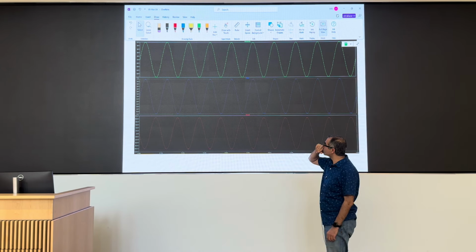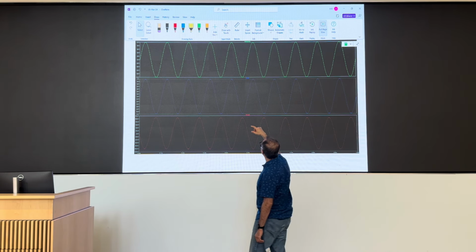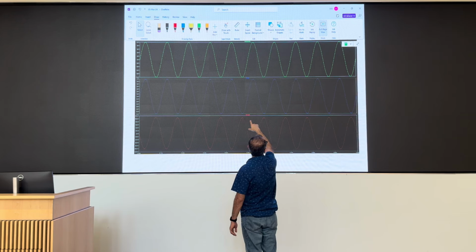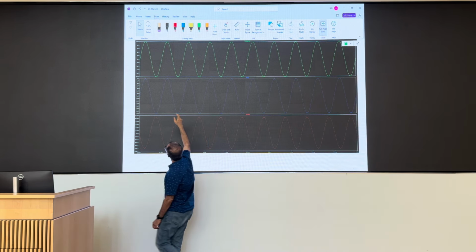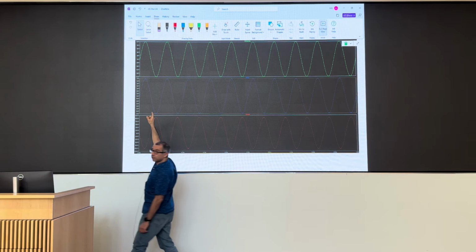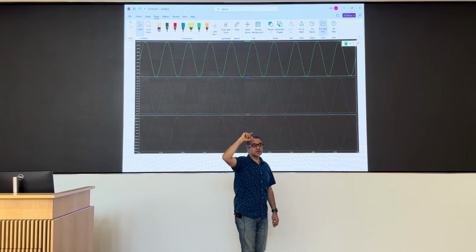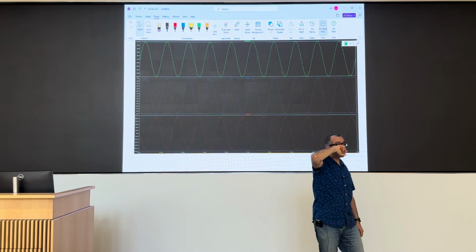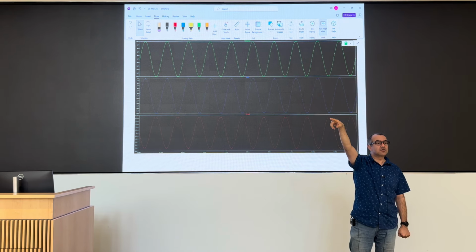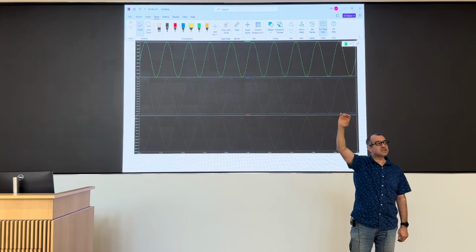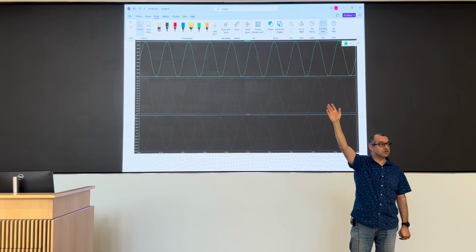Right? V in should be the middle one. What's the amplitude? 7 millivolts. What was the ratio we had? 0.69. Right? So you go from 10 millivolts that your source provides to 6.9. That's how much you lost. 30% of the signal you lost.